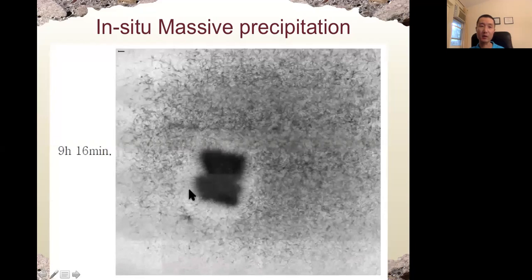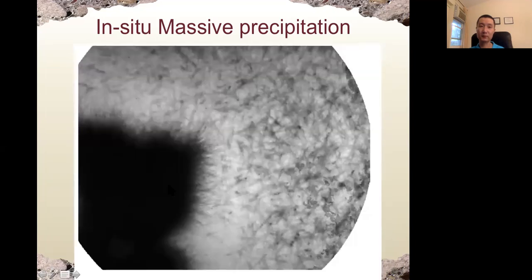So this is 9 hours. We have more hydration product. Okay. Right. This is a close up of the hydration product on the surface of the cement grain. So these are needle-like products such as CSH and ettringite. Okay, that is how concrete changes from a liquid to a solid, and that's how concrete can achieve its strength over time.